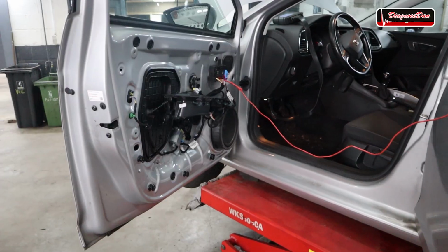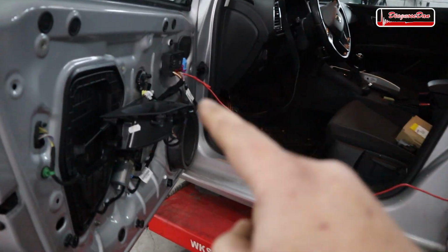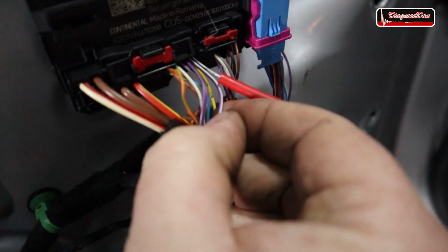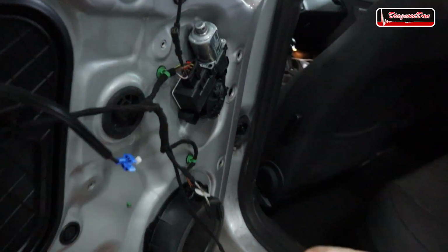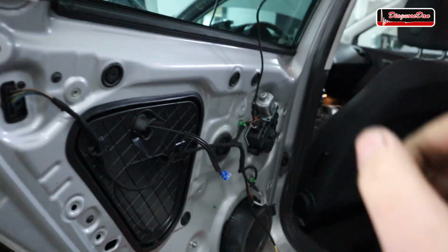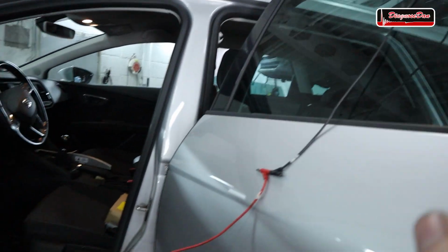Now what I did is, since I know there's communication over there, but not over there, I made my own communication wire. So I hooked it up between that purple and white wire over here, and I connected that directly to that purple and white wire in the rear. So now, right now, we've got a direct connection between the front and the rear. So right now, it should work.